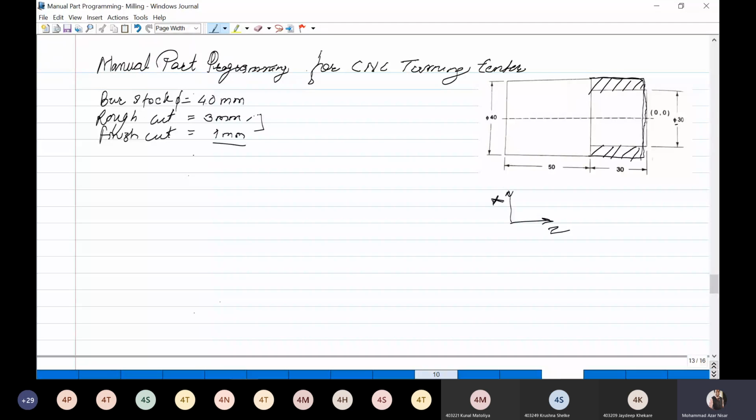At the time of that cycle, I will tell you, instead of the retracting position of the tool, you can use that code and you have to machine that part. So this retracting line of block will be eliminated. Okay, so we'll use the conventional way as we used in the previous problem. This is a multipass type of turning. So we require total four passes to complete this operation. Okay. So let's start again.